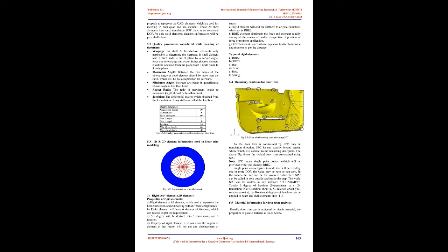The modeling of the complex geometry requires specialized software to achieve the required model. Since the composite material has high fixing areas to the metal structure, there is equivalent stress distribution, and the displacement of the lignocellulose material is 43% smaller than the polypropylene panel when compared by the finite element method. The smaller displacement is due to the high rigidity and low weight of the material. This decreases the overall weight from 1.81 kg to 1.49 kg.